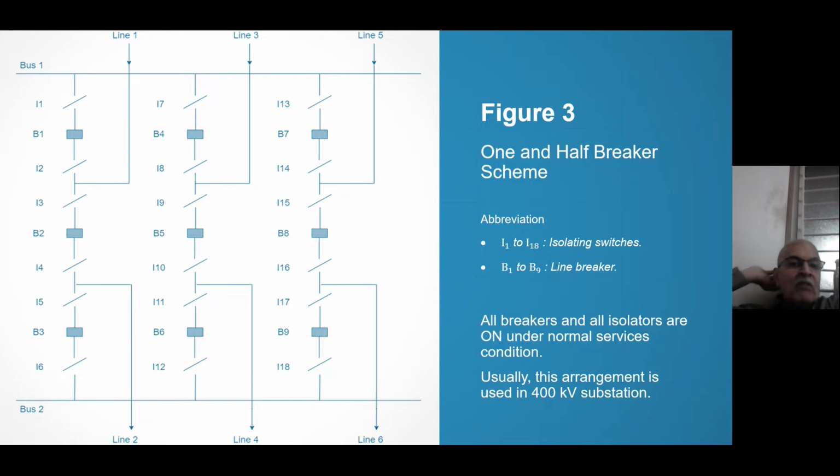2. There are multiple ways, and therefore you can maintain multiple breakers. In case of one double bus scheme, you can maintain only one bus at a time, because the bus coupler can do the function of one bus. Here you can feed two or three breakers also at a time. So power is available to the consumers. Power is fed by the electricity company. So the electricity company is not at loss. The consumers are also not at loss.